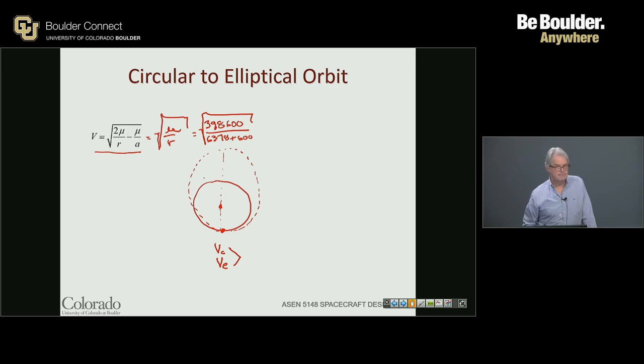All right? So I take, in reverse, the velocity that I would require at the new periapsis point by the vis-viva expression and subtract the velocity that I did have on the circle to give me what we call the delta V required. Make sense? Okay.